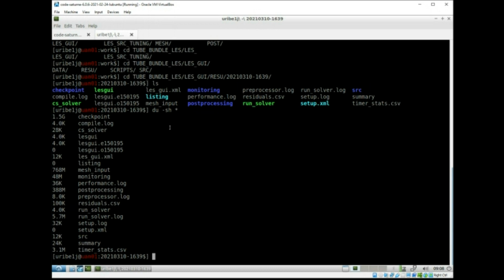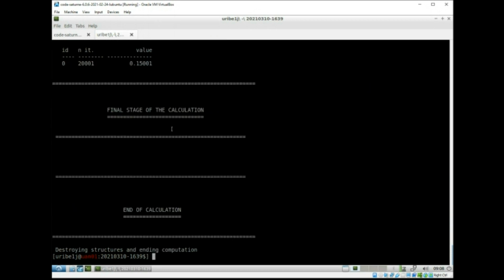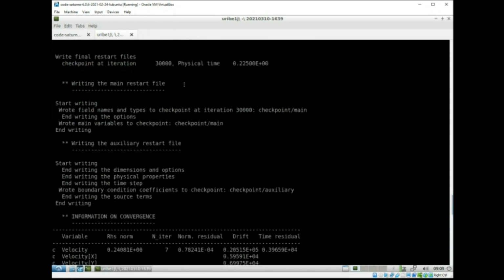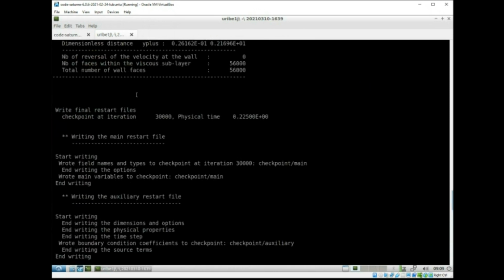but what I would recommend to you is first of all, check that the actual run completed. You can do something like this, for example: use the tail command to show the last part of a file, and then you can put minus the number of lines that you want to show. If everything went correctly, you will see that the last iteration is iteration number 30,000.